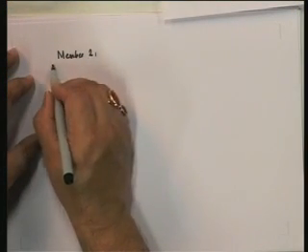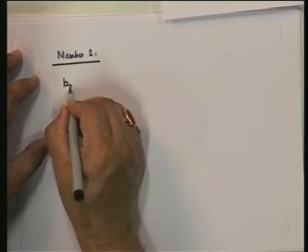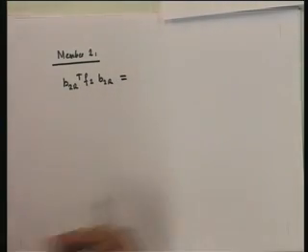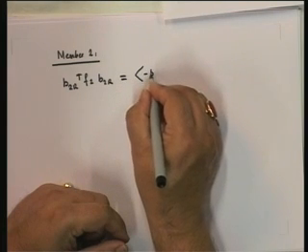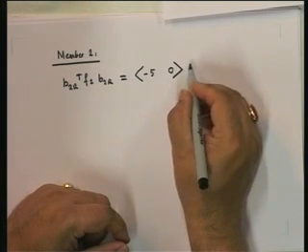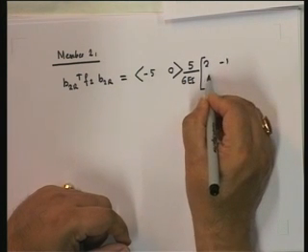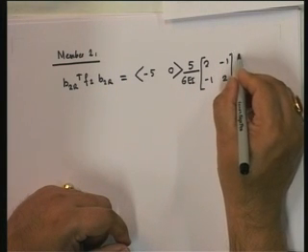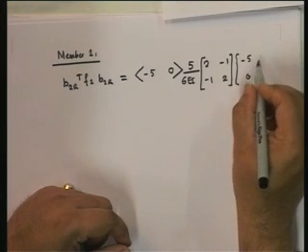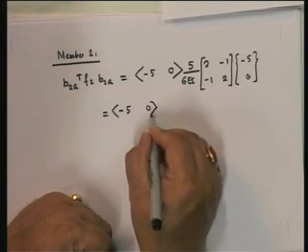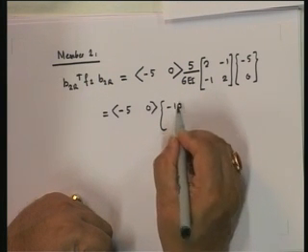Similarly, I am going to find these for member 2 and member 3. So for member 2, I have B2R F2 B2R, which if you look at B2R, is minus 5, 0, and into the same F. All the F's are the same because the lengths are the same and the EIs are the same. So here this is equal to minus 5, 0, multiplied by minus 10.